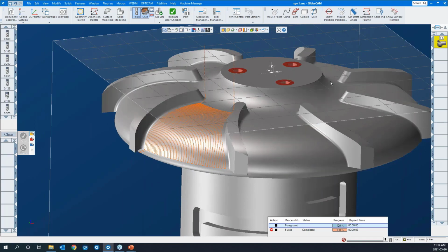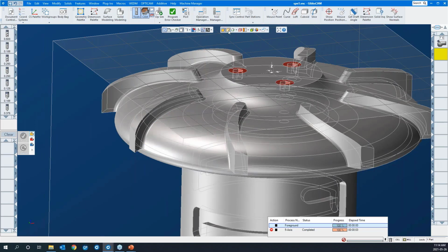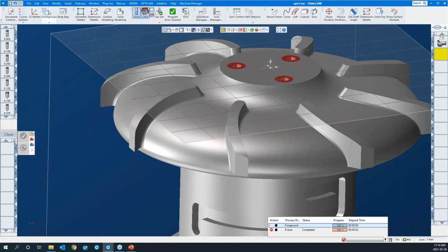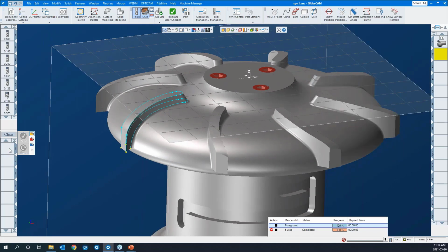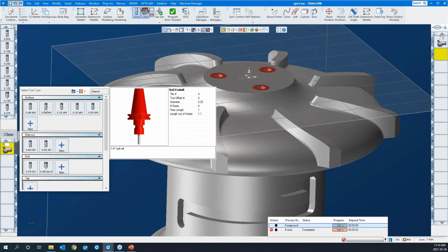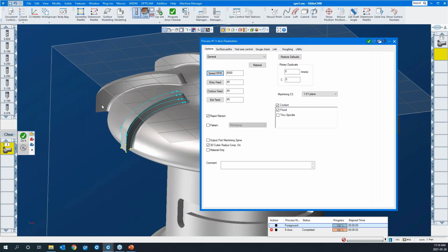In this last example, this last toolpath, I used the edges of the solid to select. Well, you certainly can do that, but you can also use geometry that you have extracted from the solid. And I can do that in this case here. I'll create another 5-axis strategy. I'll use the same tool. Cutter comp is on by default. I'll turn it off until required.